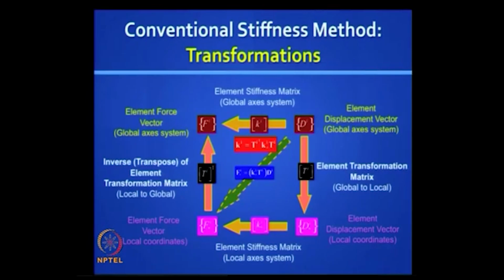So Ti matrix is no problem, and the beauty about this matrix is the inverse of this matrix is the transpose, because it is an orthogonal matrix. Okay, so you also need to indicate the local and the global coordinates in parenthesis as we did earlier. This is a path we will take to do transformations.